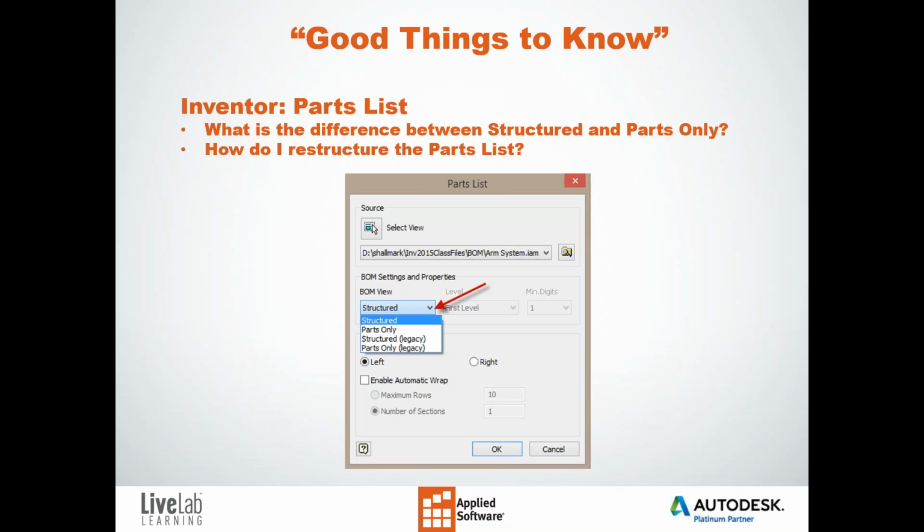You can see the file that's listed there, the armsystem.iam. I may be just detailing a cylinder, or a couple of the fabricated pieces in that, but I can go into the parts list and turn visibility off of various items, so that when it generates, I get just the items that I'm detailing on the sheet. So that's another tip, or option, that you have.